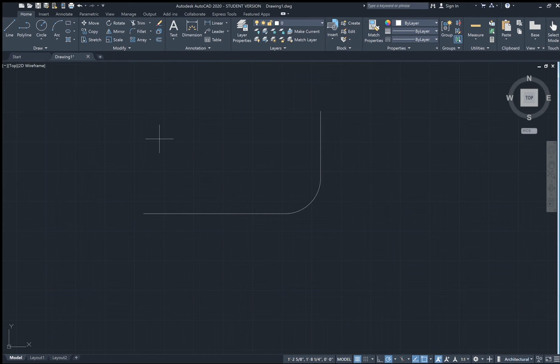So let's say, I don't know, 3 inches again. Say we wanted to create an object 3 inches away from its original position. So we would select this object. As you can see, if we move our cursor up, it'll create a line 3 inches above where we selected. If we go down, we'll also do the same thing. And so the offset command is good if you need to basically offset a given object. It's very useful, very useful.